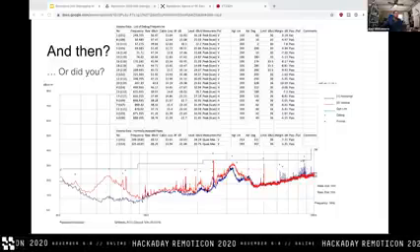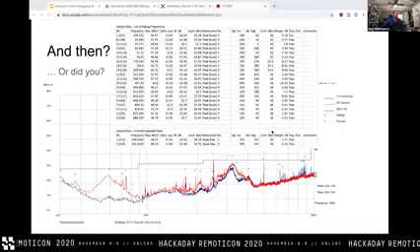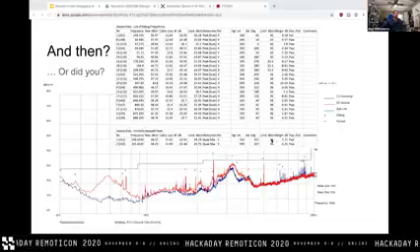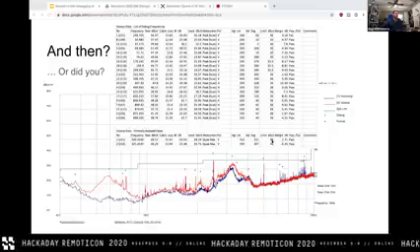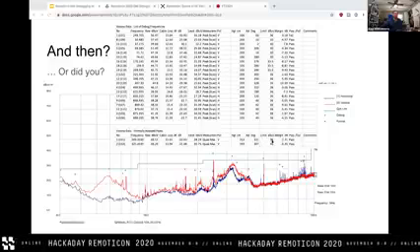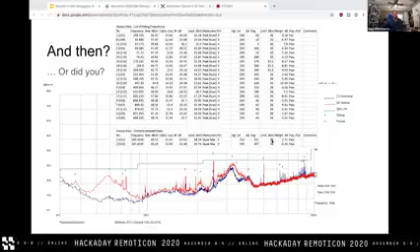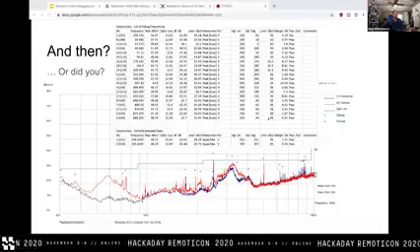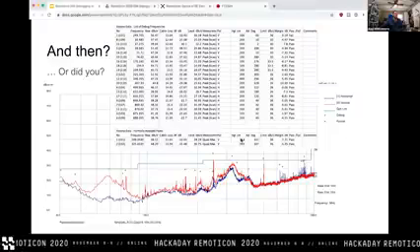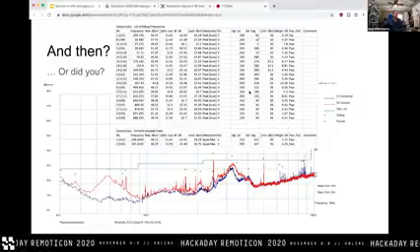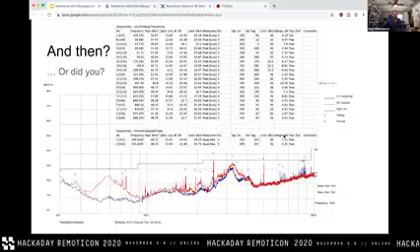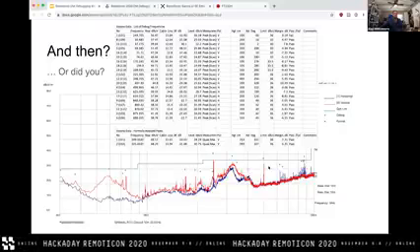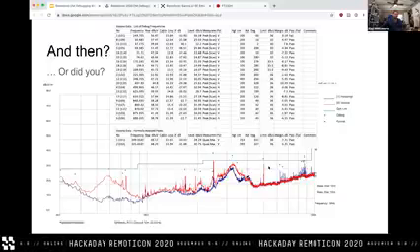It's still a problem, but under a quasi-peak analysis, that particular frequency isn't actually failing. So it could be that you've got a bunch of these debug frequencies that are a problem, but it didn't matter because on all of the frequencies that were formally analyzed, you don't actually emit enough power enough of the time to fail.